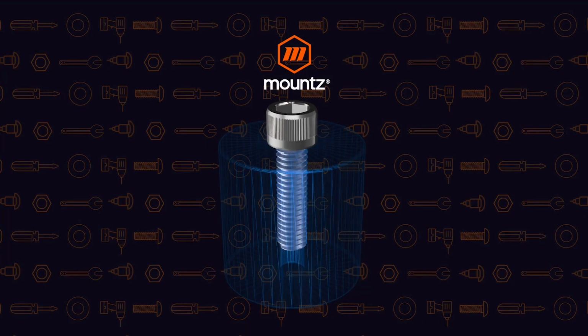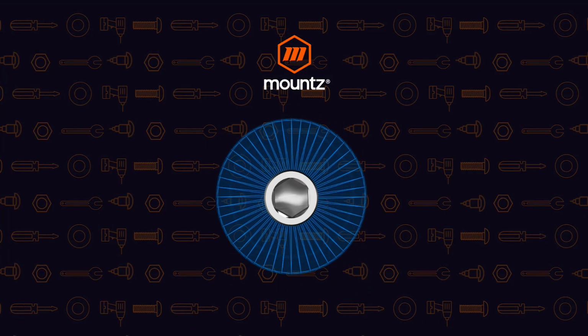And so the first movement test is where we actually turn the fastener a few degrees in the tightening direction, and we want to be able to capture what that value is during that movement. This can be a good test to determine what the torque value may be on that fastener. But we typically want to measure what that value is at between 3 to 10 degrees of movement because there are some frictional forces that we need to overcome during that particular test.